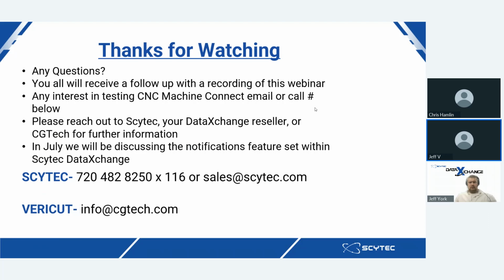as each one of them is running, that data coming from the machine and how the machine is behaving and performing is being recorded up through DataXchange software. You will then be able to go through VERICUT and gather and grab one of those runs of a part. So let's say yesterday afternoon, suddenly at 1:30, a part came up discrepant. Well, what happened? So you'd be able to go in through post-check, grab the data for that part that was specifically run at 1:30, load that into VERICUT, and see how the machine actually behaved in cutting that part.